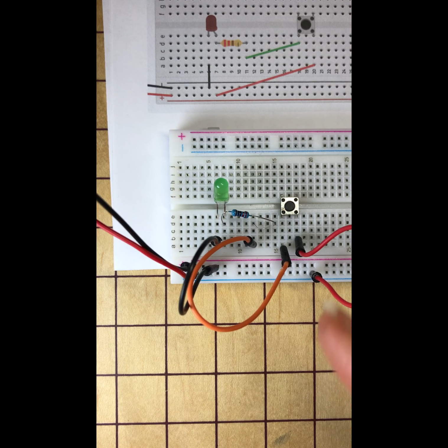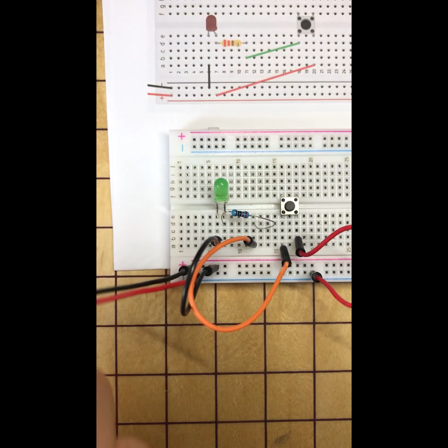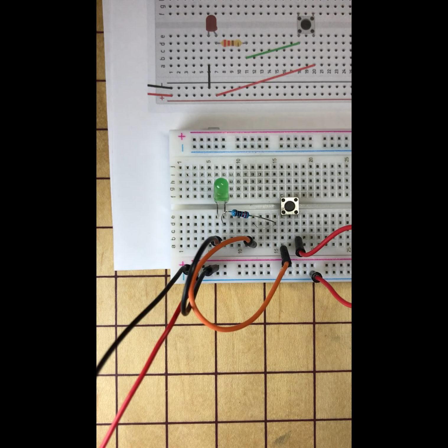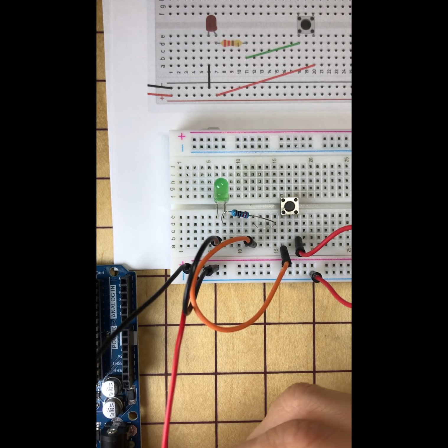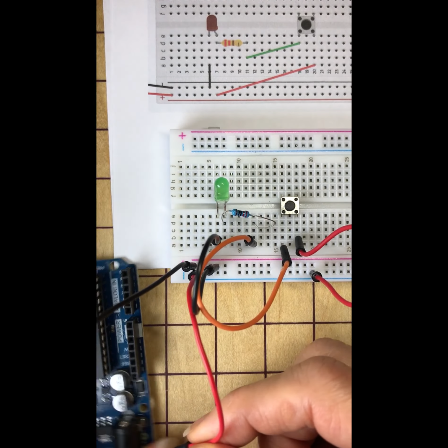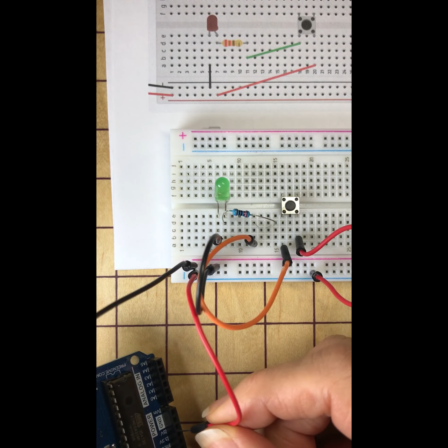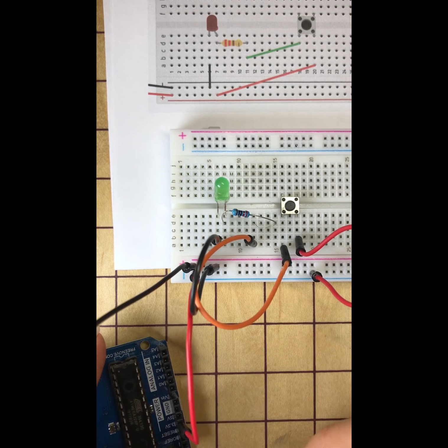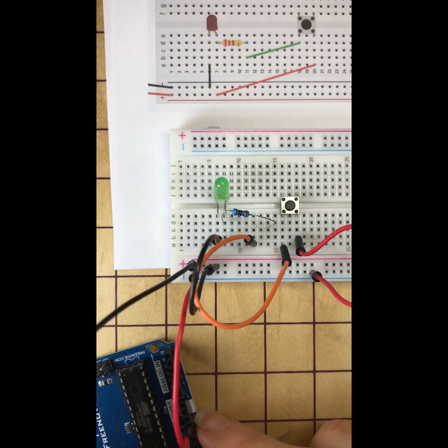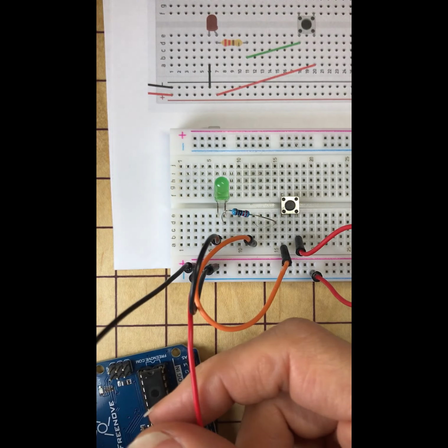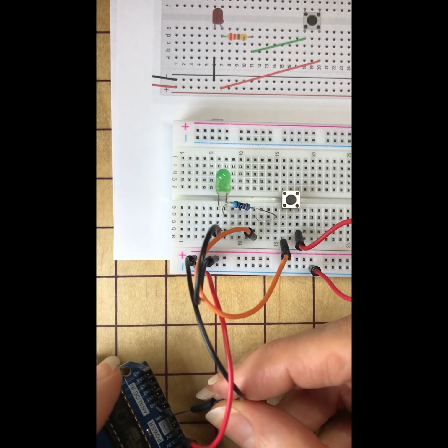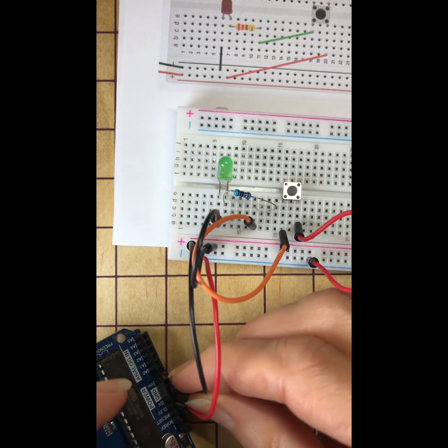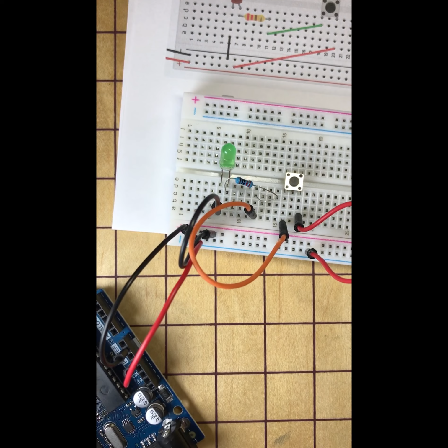And so that looks pretty much like my circuit. I just have that push button switch moved over a little bit more. I was concerned I was going to run out of room. And so now these guys right here, I'm going to connect to my Arduino with the red positive power going to 5 volts, just like in my circuit online in Tinkercad, and the black negative ground going into either of the two grounds on my Arduino.